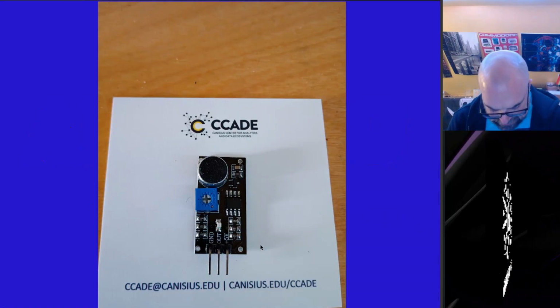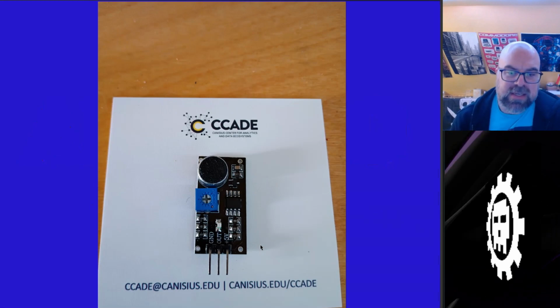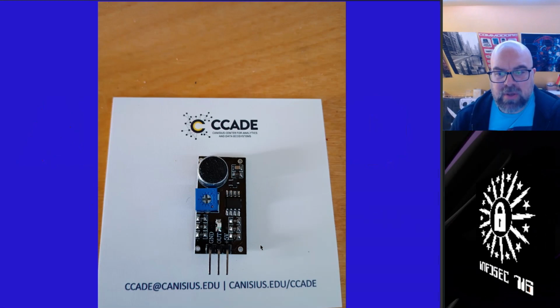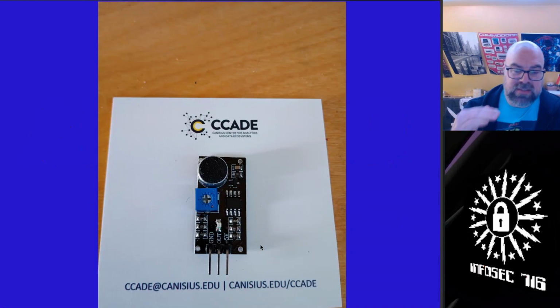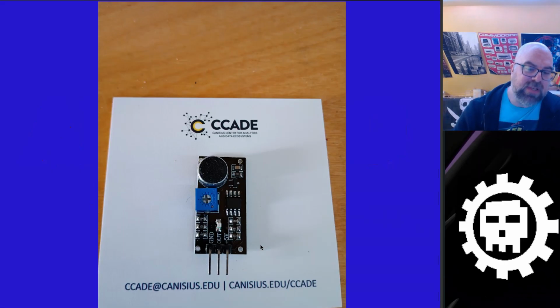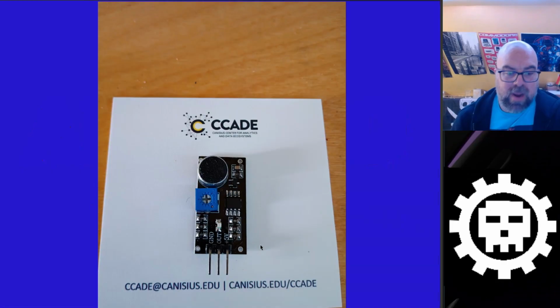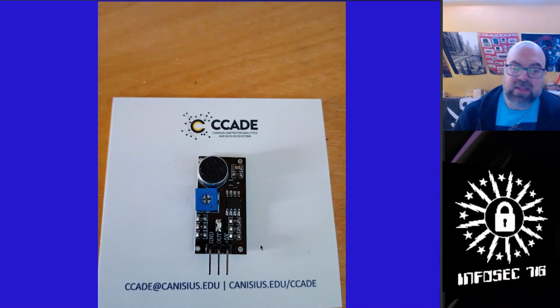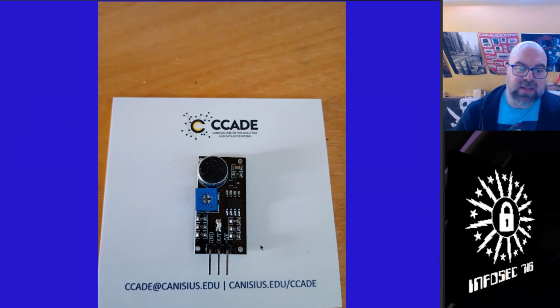Now, as I said, this is a digital sound sensor. This is not an analog device, it's a digital device. And as always, what that means is it can produce a 1 or a 0. Either there is sound above the threshold that we've set with the adjustment screw, or there is not. That is it. There's no way of measuring relative volume or relative length of sound. Either it's on or it's off.